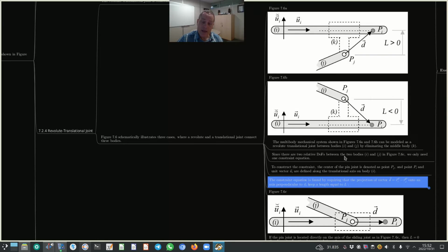The reason why we're heading there is so that we can then come back to the program DIP, or the MATLAB algorithm of Prof. Nikravesh, and we can then see in DIP, in the input file, which parameters do we need to specify there so that the generic DIP can populate the combined Jacobian matrix as well as the right hand side of the acceleration equations and execute the dynamic analysis of our multi-body system.